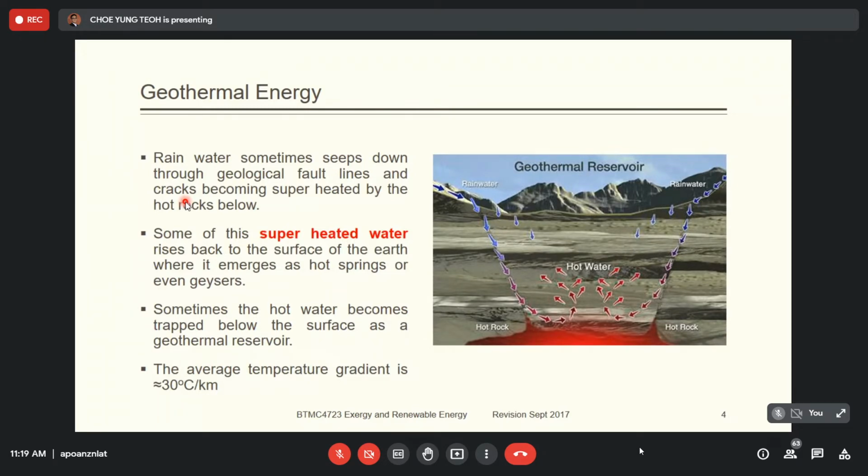Okay, so you can choose to use a lower boiling point secondary fluid in case the temperature of the geothermal is lower. But in most cases, the lower the boiling point, the lower the density of the gas, so that it will not create enough momentum to rotate the turbine.